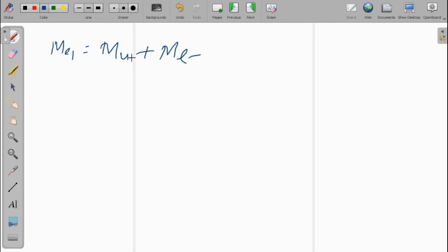Now we have to see what are the equations and how we can calculate. Mu is given to us. If you just see the problem, go to the next page. Mu is given to us 200 kilonewton meter. What is Mt? Then we have to calculate. Let us calculate this Mt here separately. This Mt is equal to, what is the equation? Tu divided by 1.7, then multiplied by 1 plus d by b.